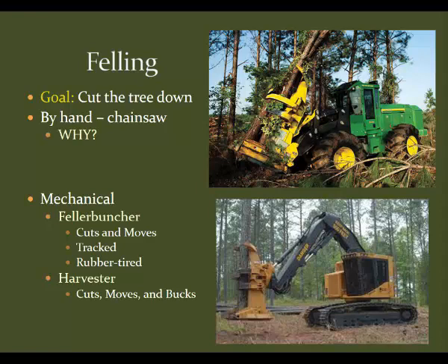So that's what a feller buncher does. And then a harvester is something that does the work of a feller buncher, but then also has additional capabilities to move into the processing stage as well. So it might then also limb and buck up the log at the same time that it cuts it.